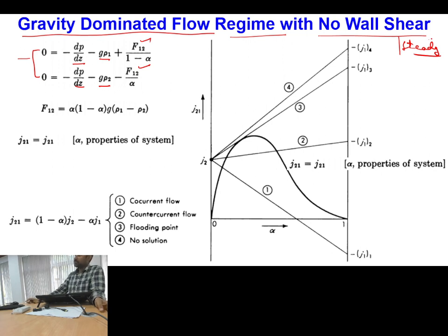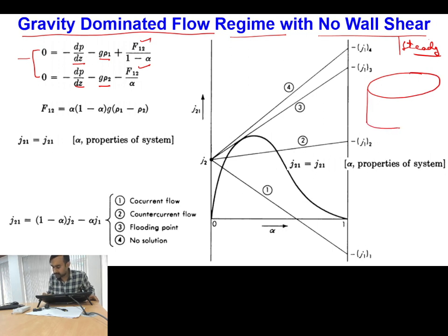Typically, consider a bubble column reactor. In a bubble column reactor you will have a large vessel, and say from here you are adding some gas, so you will have many gas bubbles within this. These gas bubbles are not influenced by the walls of the container because the container is of very large size. Neither does it depend upon the rate at which you are supplying the air into the tank. It is majorly their individual shape which is governing their motion.